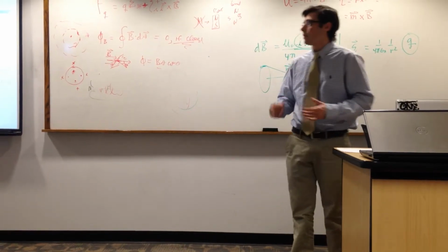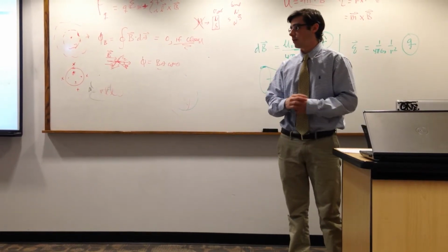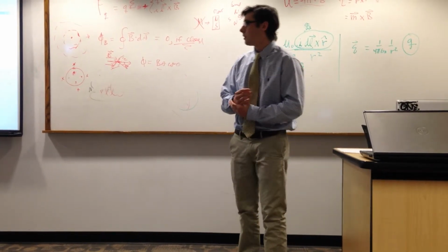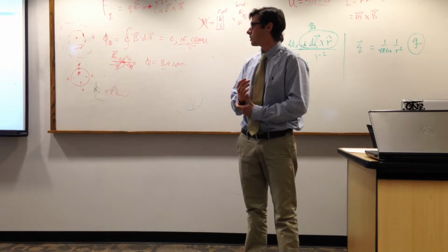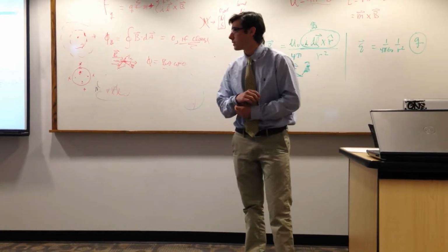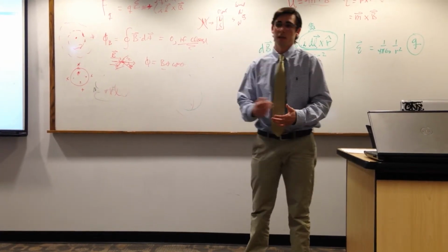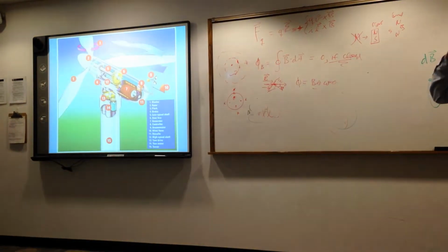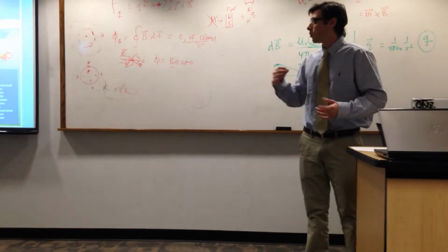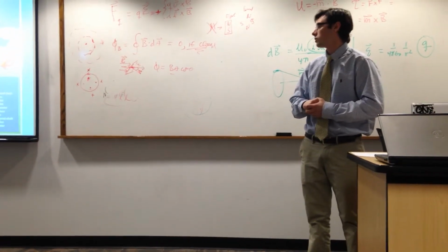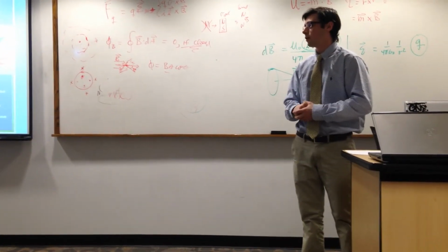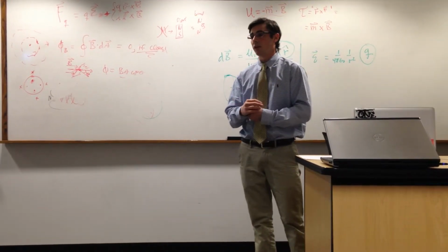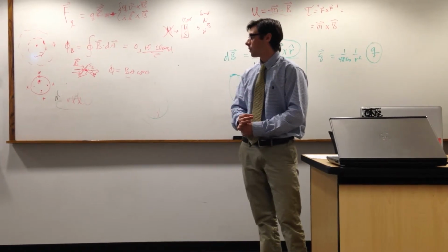When that happens, the blades circulating create about 18 revolutions per minute, which seems small in the grand scheme of things, and you think you wouldn't get that much energy out of it. But looking back at our previous diagram, all of these gears and the crankshafts end up multiplying the revolutions per minute nearly 100 times. So what's originally 18 revolutions per minute turns into about 1,800, and that's where you gain all your energy